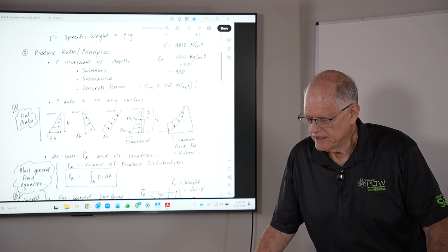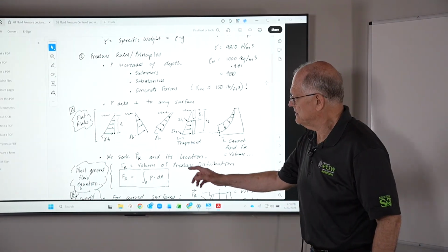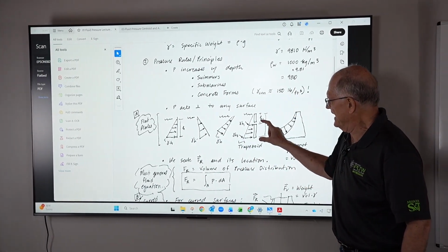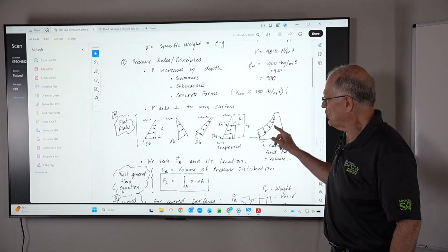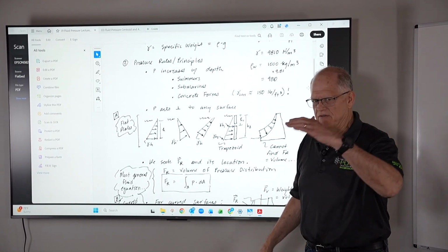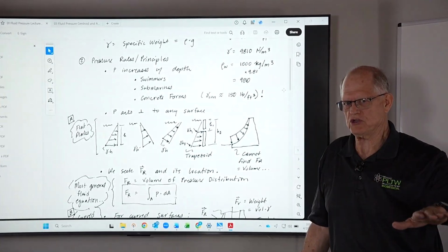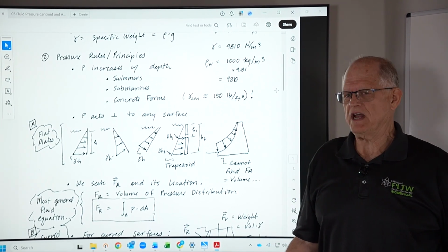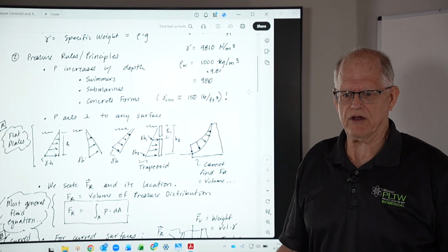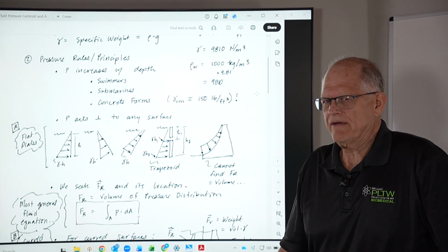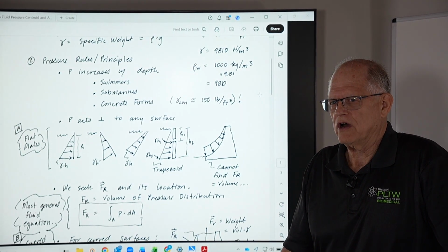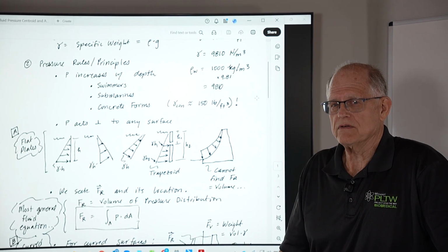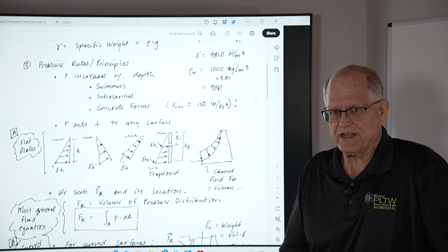what you have, if you have a straight dam or a straight plate or a gate of some kind, or even a curved surface, you basically have a fluid pressure distribution on that surface, and so it's a distributed load. In fact, we've done distributed loads throughout the class, but we really haven't talked much about instances that produce distributed loads. But fluid pressure is a classic example of that.